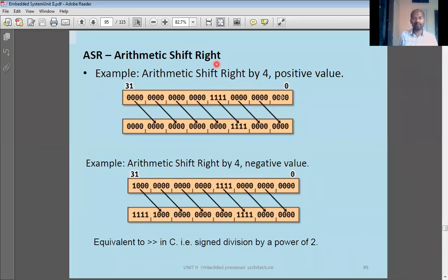They may be any values. All those 4 bits will be dropped because we are right shifting by 4 units. If it is 7, then the first 7 bits will be dropped and so on. And at the end, in the result, at the MSB end, 4 zeros will be added if the register value that enters into the barrel shifter, that X, is positive. That X may be negative because this arithmetic shift right instruction operates on